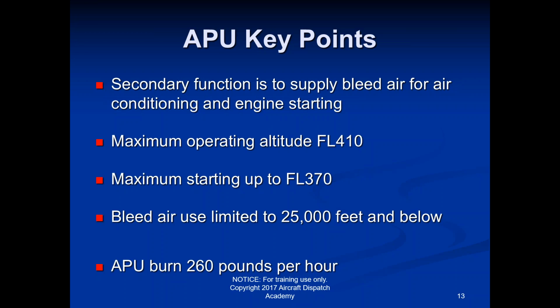Yeah. So anyway, as the APU starts running, it has this air coming off the engine, and the airplane will harvest some of that bleed air that's being sucked in and then going out the exhaust. It'll take a portion of that bleed air. When you want to start the jet engines, they have to have air flowing to them in order to start circulating through and turning the turbine, the fan. So in order to get that air, they redirect part of that APU bleed air, and they can hit a button, and then it just sends it to whatever engine they want to start.